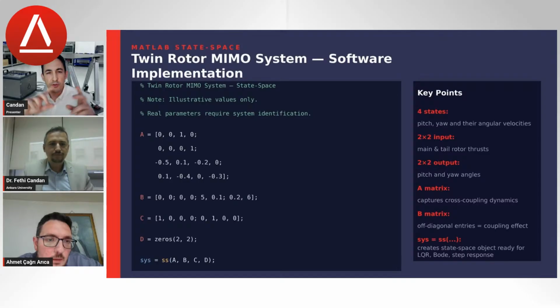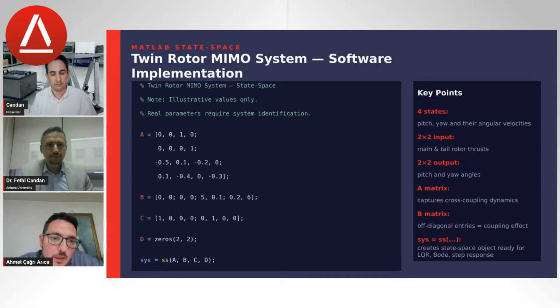And there is this software implementation. There are system parameters and system matrices, and we can select the A and B matrices to design the LQR controller. C is the output matrix, and here we control the elevation and pitch axes, so we select the elevation and pitch rows. D is the disturbance matrix.